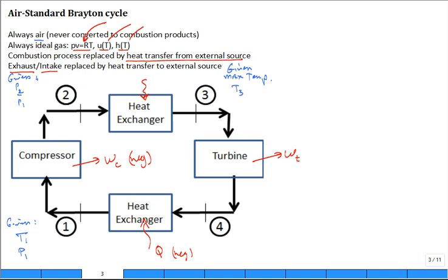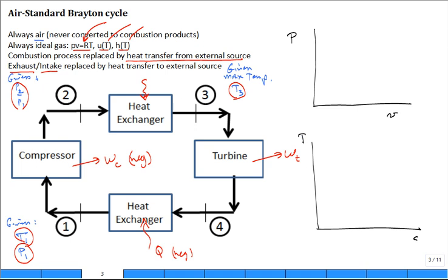But you have to pass really hot gases into the turbine, and the metal materials in the turbine, even if they're exotic materials, even ceramic or other things, still have to withstand those high temperatures and hold up in a harsh environment. So you specify the max temperature, the pressure ratio, the inlet temperature, and the inlet pressure, and then you can do a lot in the way of calculating the performance of this system. Let's sketch it out on a PV diagram, or sketch it out also on a temperature entropy diagram.